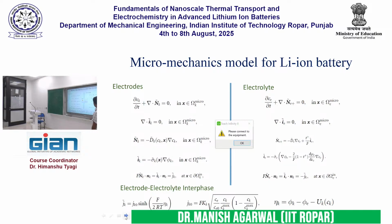Although I have not defined open voltage, for a battery it is the voltage generated when it is almost not giving any current. If you just connect a multimeter to the battery without any load, you get that. But phi k minus phi e minus uk is not the open voltage for the battery, it is the open voltage for that particular electrode. That's why there is a subscript k.